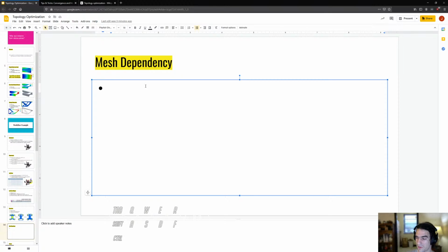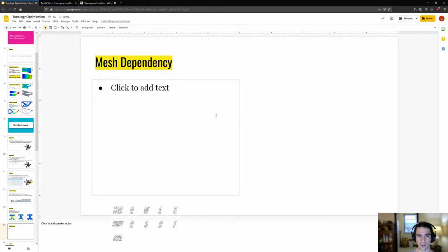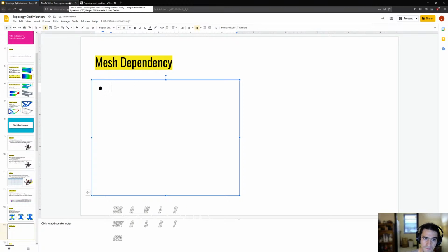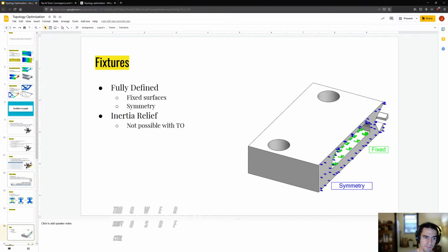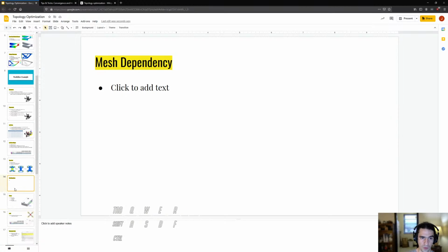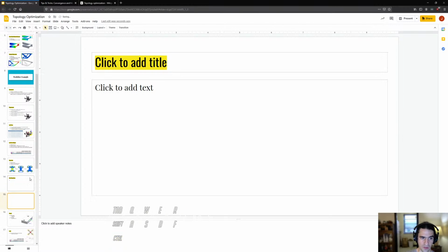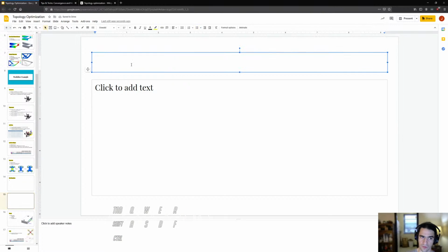I have no idea what SolidWorks uses behind the scenes, but what this means for us is that even with all their clever tricks, the coarseness of the mesh you use will influence the actual results you get. Not just the resolution of the results, but the actual result will be different based on your meshing.